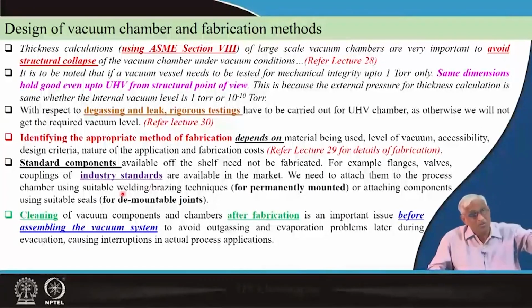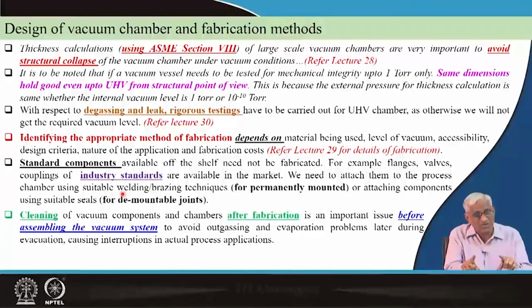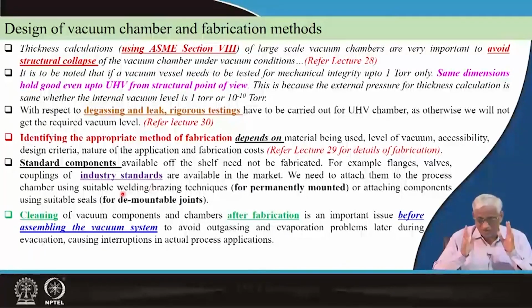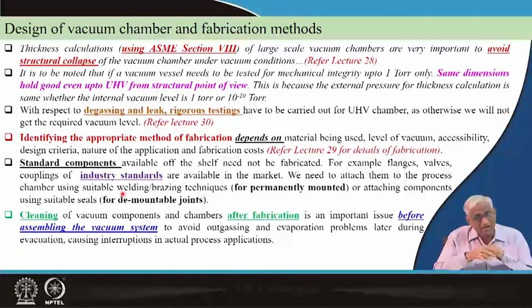Again, you have to have some pumps only for purging, some sources, leak gases. That wall should be UHV compatible. Anything coming into contact with the UHV chamber from the outside world has to cross the barrier of the vacuum chamber. There you have to be careful about seals and materials, components, tightening, the torque to be applied, how much torque.